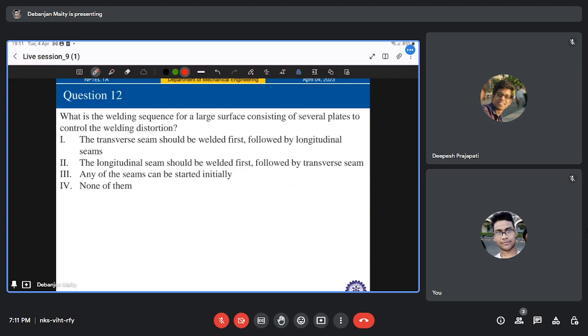What does it mean? It means that, among other things, you should employ the minimum number of parts and thus a minimum amount of welding. That is the ideal, right? If you are doing a minimum amount of welding, or using a minimum number of parts, your distortion must reduce. That is the ideal case, but the reality check will be different depending on your application, of course.